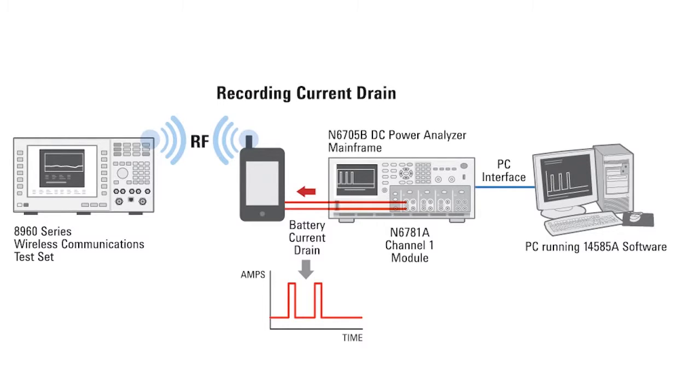A more repeatable solution for doing this is to capture the device's dynamic current drain over an appropriate period, and then play it back using a programmable electronic load to discharge the battery. We use the setup depicted here to first power and capture an active mode current drain profile on a GPRS smartphone.